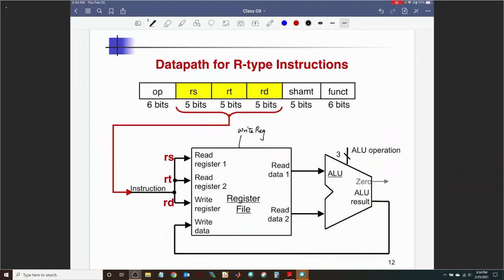What is the 0 in the ALU again? So 0 is an additional output of the ALU that lets you find out whether the result of the ALU operation is 0 or not. For example, if you are subtracting equal numbers, then you would get that 0 to become active. Let's see. So what turns it on?